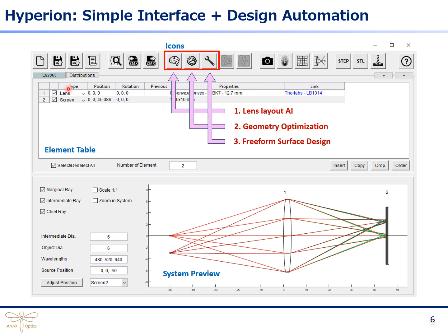The optical components are listed in one main table, and instead of the usual Surface 1, Surface 2 approach used in most conventional optical design software, Hyperion has taken the approach of calling a lens, a doublet, and so on. This makes for a linear approach and makes identification of the optical component possible very easily on the layout shown in the bottom.